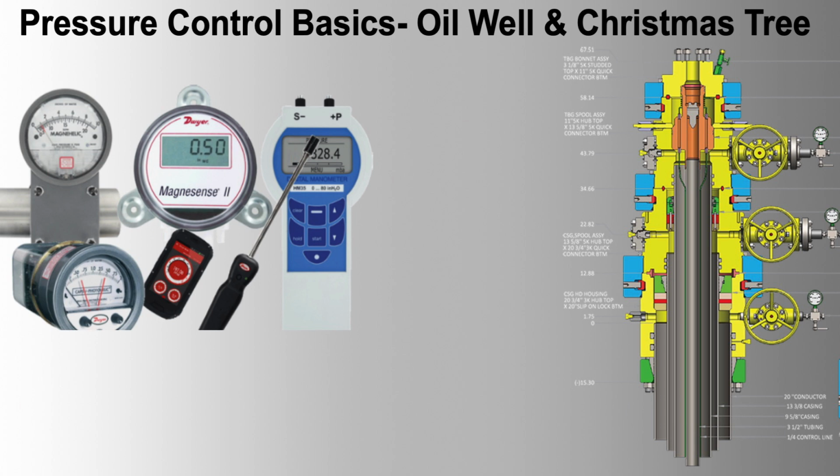Example 2, downhole pressure gauge. Instrument type, quartz pressure gauge, accuracy, 0.01% of reading. Material, Hastelloy C276 for extreme corrosion resistance. Installation, integrated into the downhole tool string with cable connection to surface readout. Other criteria, high pressure rating up to 20,000 psi, NACE MR0175 compliance.